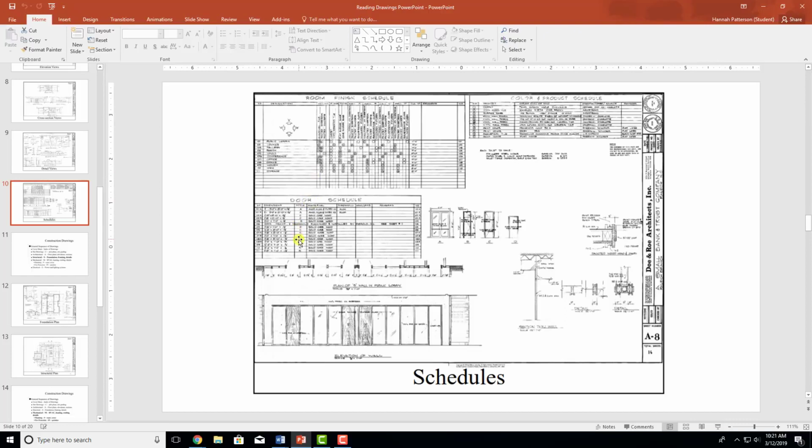Then you have your doors, because there are numerous different kinds of doors. They might have different finishes. Some might be metal while some are wood. So it'll say Room 101, office, door, wood. Or it'll say room, whatever, kitchen, double swinging metal doors. And so those will all be abbreviations also. So you'll have to know how to get back to the abbreviation section.